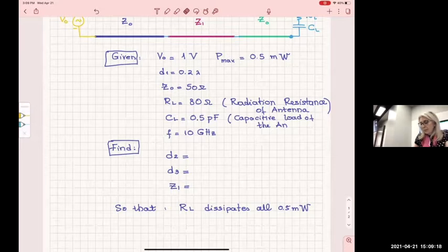All right. This one does not have a dipole. If you were to scratch the paint off, you will see what we call a slot antenna. A slot antenna is something created with two conductors coming very close to each other, like a gap between two. You have a metal, a ground, and then you make a deep scratch that separates the two grounds.